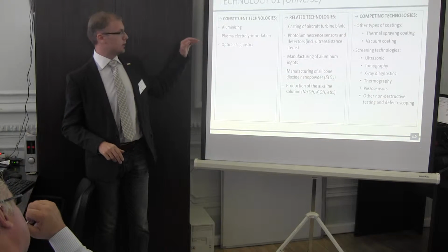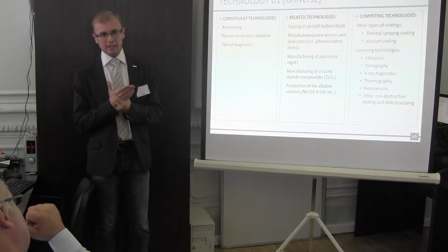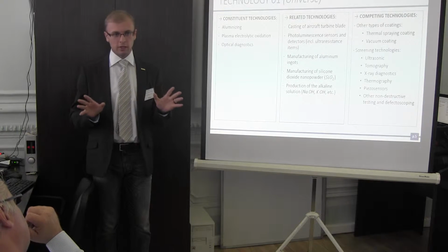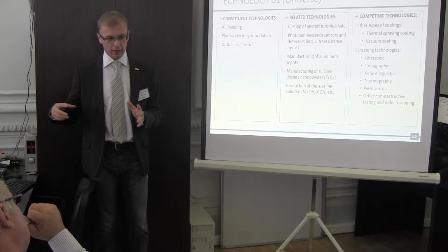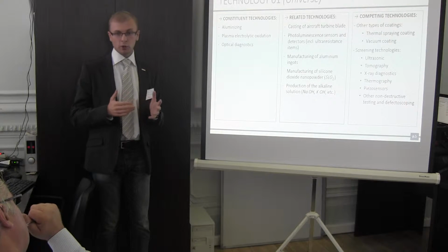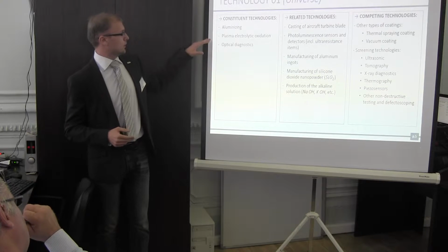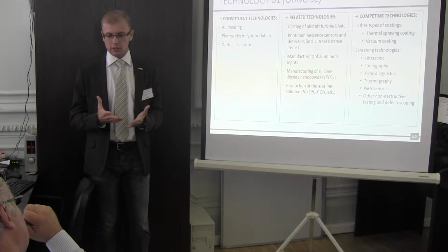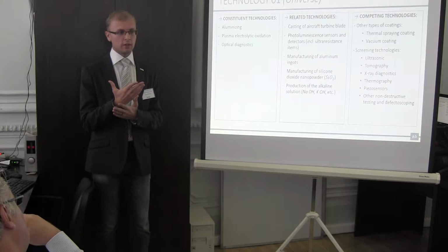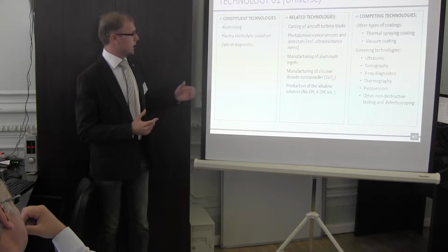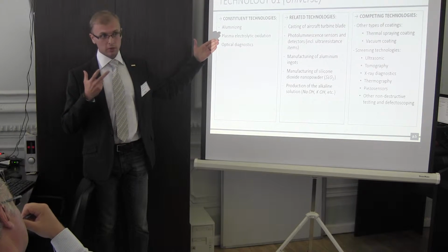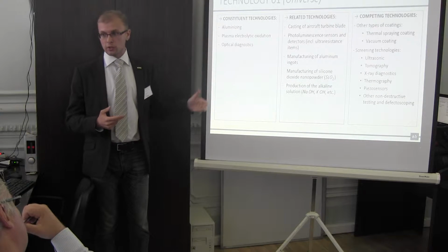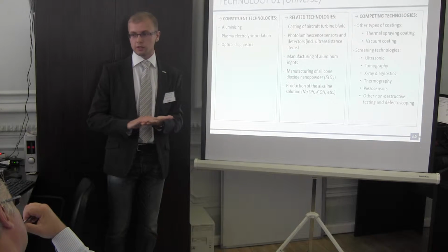so that if it cracks, because the crack on the blade comes out from the surface. That's the general process of cracking. So it's quite obvious that the coating will work in this case. When it cracks in the luminescent light, it's immediately seen, immediately detected. Visible, yeah. And by the way, a very significant thing to say is that this coating is also hardening. So it's not just something on the blade, it's hardening.